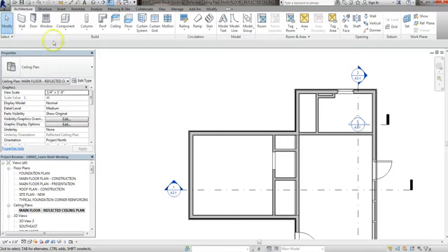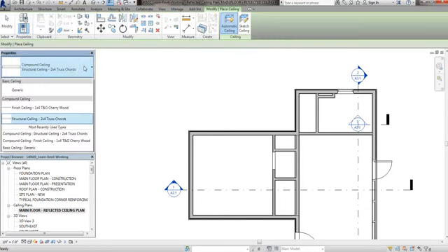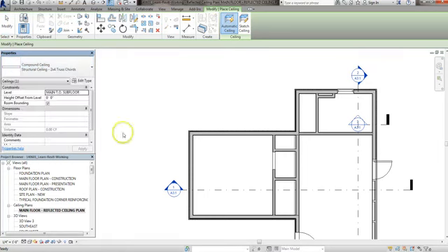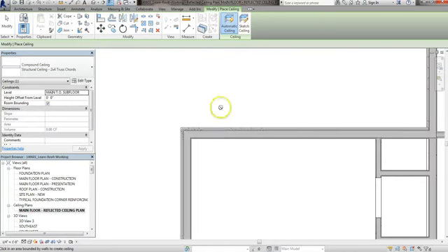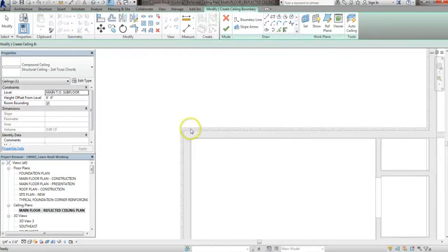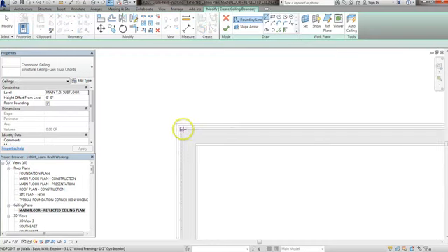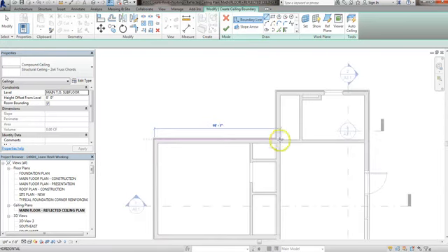So the first ceiling you're going to make, here's your ceiling. You're going to make the structural part of that. So that's the 2x4. So that would be the bottom of your roof framing. And that's going to go over, we're going to sketch the element, not automatically create it, we're going to sketch it. That's going to go over your framed walls, just like a roof truss would be.